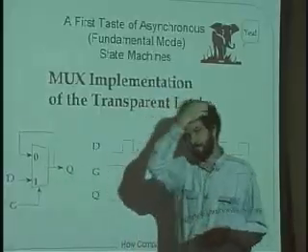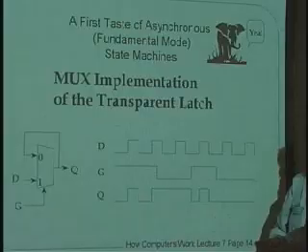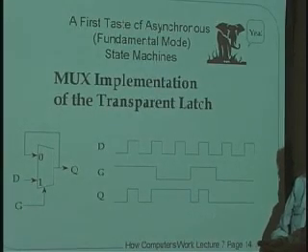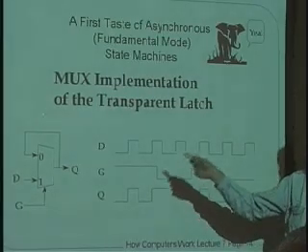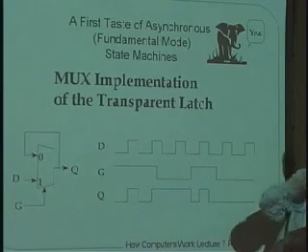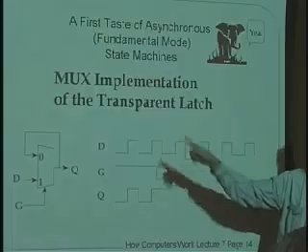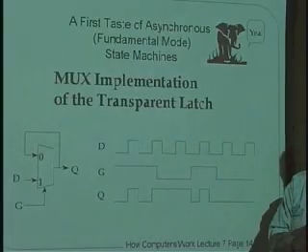Yeah? But wires have resistance, and so these voltages are continually bleeding away. Absolutely right. If I built this selector out of a physical switch, like a knife switch or a toggle switch, and I just hook that wire from the output back around to the input, of course the wire's not going to sit there at a high voltage all by itself.